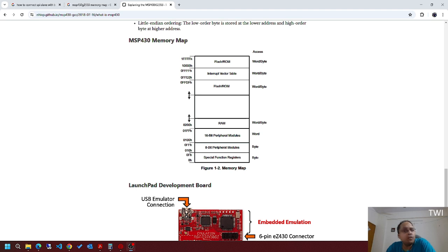Some controllers allow you to invoke the bootloader using detectable UART patterns, which can be sent over the UART when the controller is booting. Some USB-based bootloaders are also available in the market, wherein during the booting process, if you send some specific valid data over the USB, then you can invoke the bootloader.